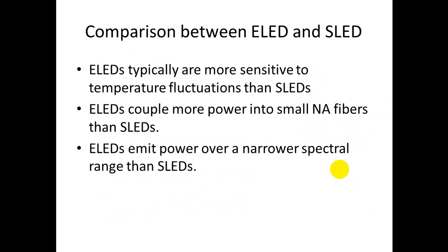Now let us see the comparison between edge LED and SLED. ELEDs typically are more sensitive to temperature fluctuations than SLEDs. ELEDs couple more power into small numerical aperture fibers than SLEDs. ELEDs emit power over a narrower spectral range than SLEDs.